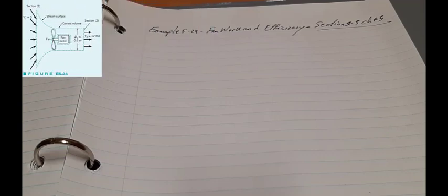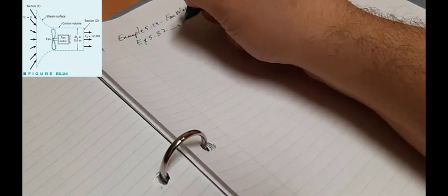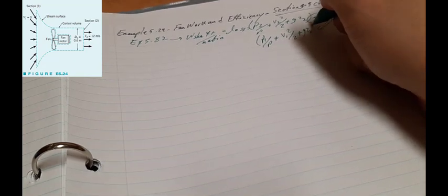Here we have to use the figure E5.24 and also the equation 5.82, which is W shaft net in minus losses is equal to P2 over rho plus V2 to power 2 over 2 plus GZ2, total, minus, excuse me, let me just write it over here, P1 over rho plus V1 to power 2 over 2 plus GZ1.